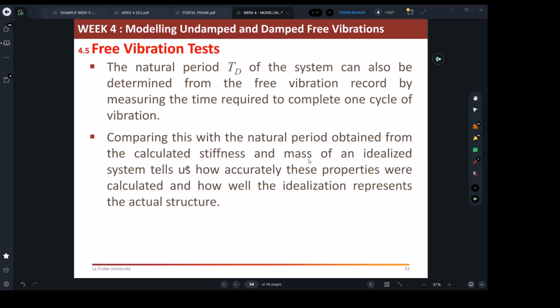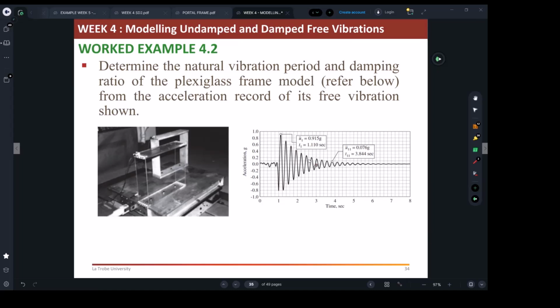Because as I said in the council, after a disaster or whatever, you will have the original structural drawings and calculate the stiffness. And from the stiffness, you will calculate the actual vibration properties. Then you're going to do experiments, and the experiment will tell you the tested frequencies, and you're going to compare. If they are the same, that means the building's still intact. If different, then there is some damage, and you can determine whether it's getting weaker or stronger. If it's stronger, that means it was just aging concrete, which, you know, with time, the concrete gets stronger. So that means it's good anyway.